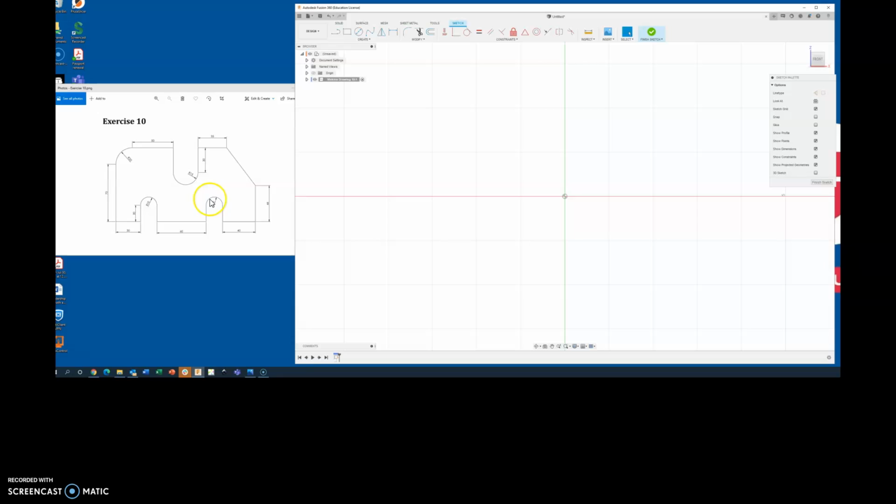And for me, in my eyes, I'm going to choose to start right here with this radial arc of 15. Remember, if the radius of a circle is 15 millimeters, then the diameter of the circle, or the distance all the way across, is 30 millimeters. The other thing that just reminded me is I need to come up here to my document settings. My default document setting units is inches. I just think better that way, but we are working in millimeters here, so I need to switch that over.